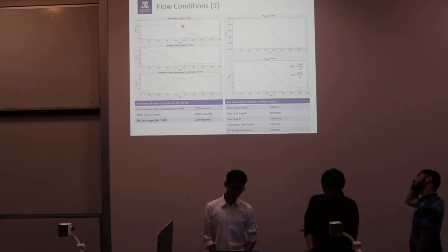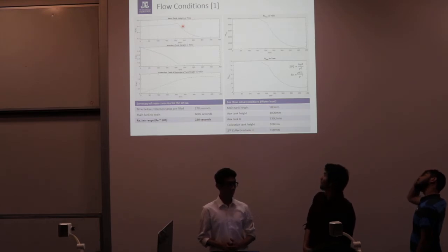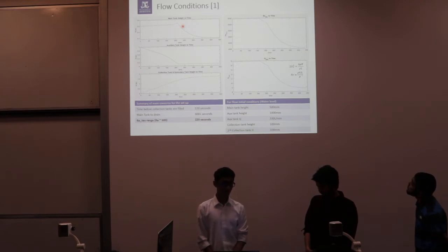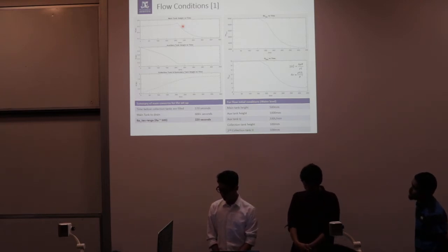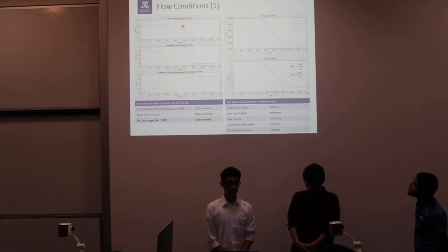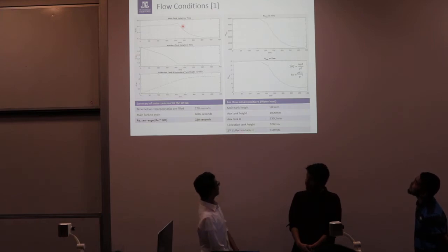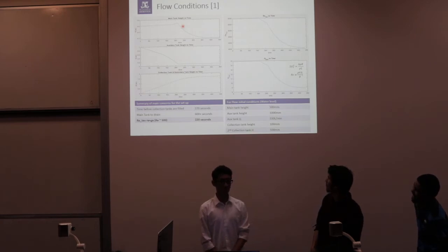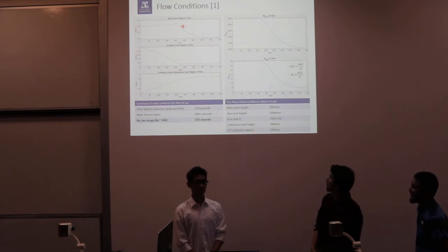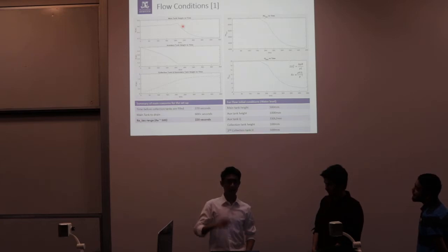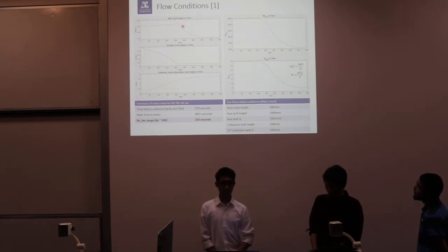So when using the current setups that Adin has proposed for the main tank and auxiliary tank, we're going to have at most 3 meters per second velocity or 18 liters per second flow rate. So from there, at most 18, but 15 is the one that we're going to set using our control valve, and then that will be compensated by the flow back pump after the collection time.